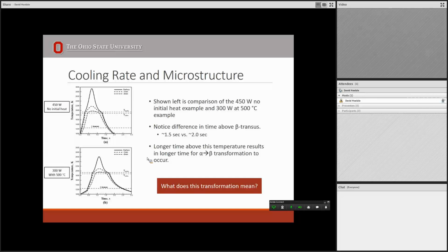And when you're going through the different phases in a phase diagram, I assume this is what they're getting at here. In terms of this very sharp gradient, they can freeze in the phase that they want. And if they were to hold it too long, the phase should go away. Yes, because there's a lot of emphasis on the gradient itself and how that impacts your microstructure. And obviously, as that changes, the quality of your part is going to change throughout. It's going to be hard to predict how that part will react to stress, and things like that. And they also mentioned this alpha-beta transformation occurrence and how that plays in.